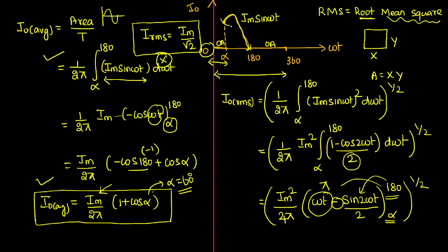See there, we received only a certain fraction. At this point you should not apply that relation. We brought this relation for the complete expression where we have pure sinusoidal from 0 to 360 degree. Here we are not having a sinusoidal waveform from 0 to 360 degree. If any one of you did it like that, kindly observe this. This is wrong here, because I have given the reason why you should not do that.